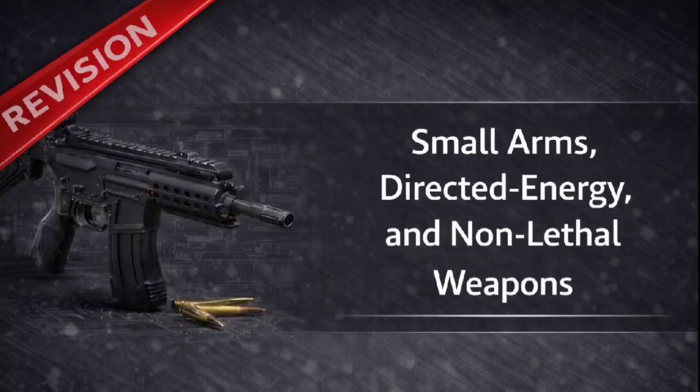And then we get to the more ingenious designs. How does advanced primer ignition, or API, get around the need for that heavy breech block? API is a brilliant breakthrough in timing. Instead of firing from a stationary closed breech, the round is fired before the bolt is fully seated in the chamber. While it's still moving forward. Precisely.